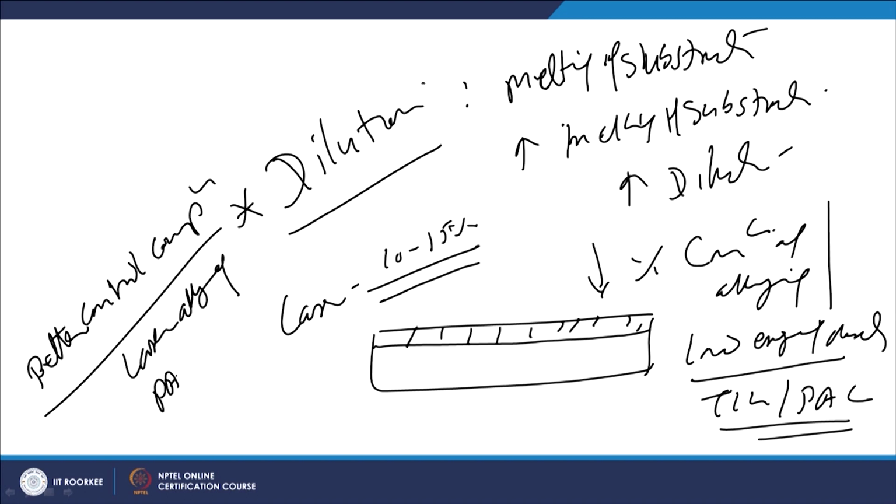But if we use plasma arc alloying, in that case the greater depth of melting of the substrate will be increasing the dilution and leading to more reduction in the concentration of the alloying elements. Similarly, in the TIG arc process, where the TIG arc is used for melting the surface and surface layers of the substrate and melting of the alloying elements which have been applied either by the pre-placement technique or by other technique, that will be leading to greater dilution and more reduction in the concentration of the alloying element.